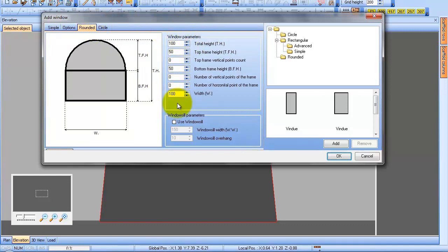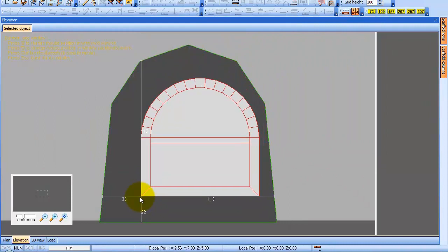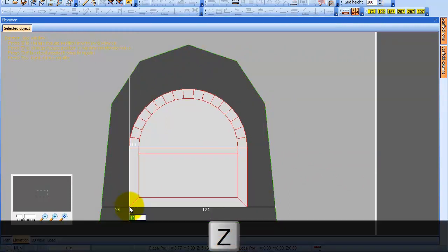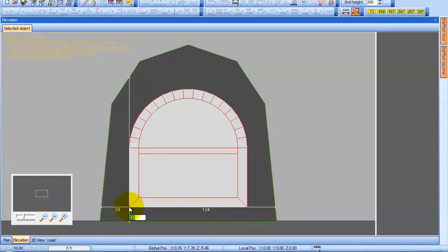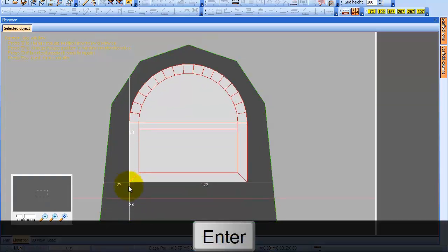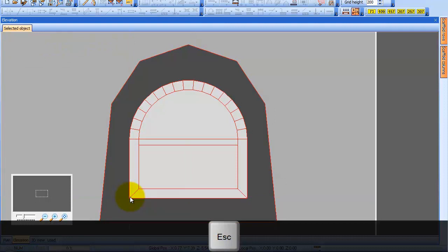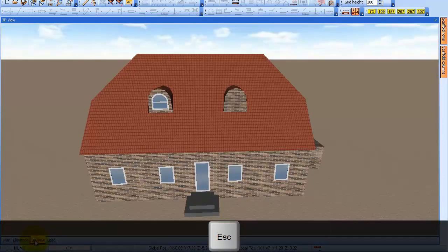Of course, after making one window and one dormer, it is possible to multiply them, so you don't have to go back in and keep adding windows to empty dormers. It is much faster this way if you have a lot of dormers. Let's align the window to the building and then place it. Here is the first one in 3D view.